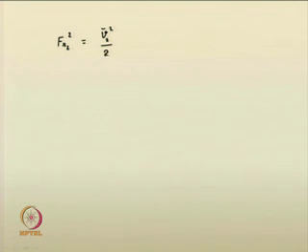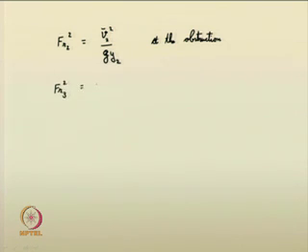We take all sections as rectangular. So, the square of the Froude number is V2 squared by g y2. Similarly, the downstream Froude number is given by V3 squared by g y3.